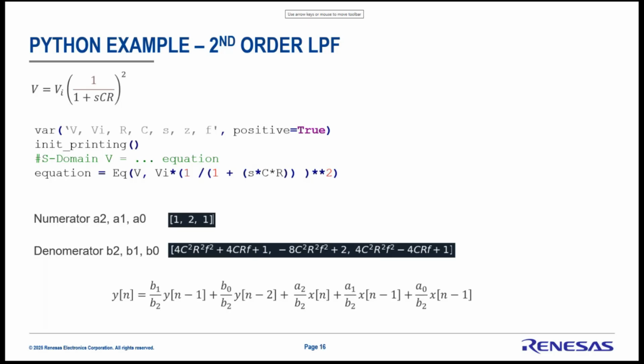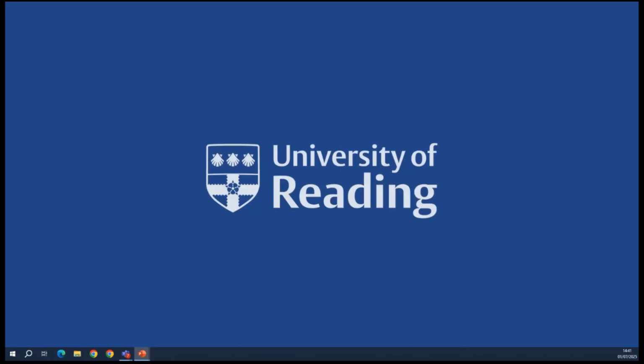This is really nice, Daniel. I just wanted to comment that the issue you can get with the cap model in particular, if you try to use it as a high pass, is you can wind up with aliasing because your signals are higher than your sample rate. You violate your Nyquist criterion, and you end up with aliasing. That's just something you have to watch out for when using that kind of model.